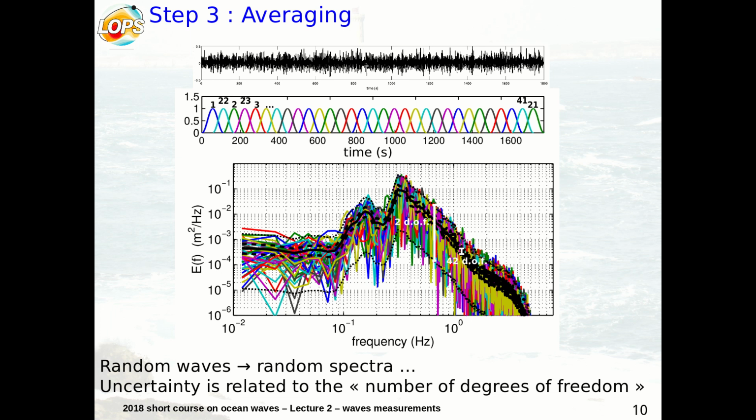And so here I have these 21 windows. I have 21 independent samples, and that gives me 42 degrees of freedom because the spectrum has phase and amplitude. So this way you get twice as many windows. And the interval of confidence for 42 degrees of freedom is something like plus or minus 40%.